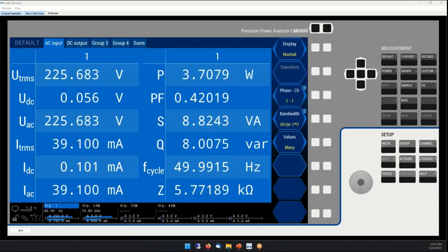So do you have some tools, some probe suitable for that? Yes, we have high voltage dividers up to almost 16 kilovolts. I don't know what your voltage level is at the medium voltage, but we can cover up to 16 kilovolts.